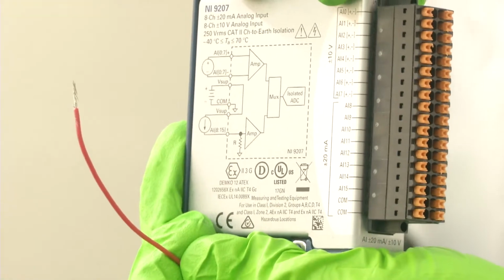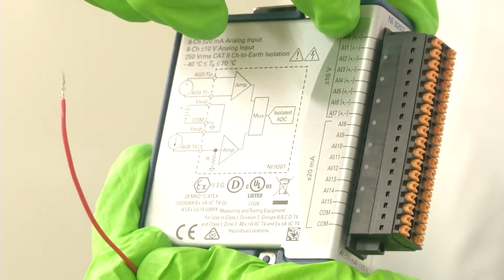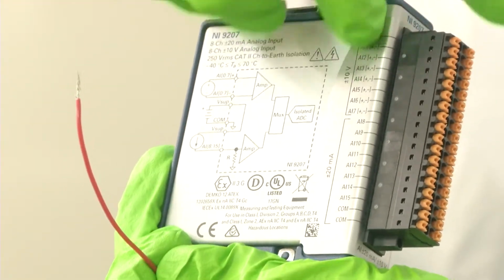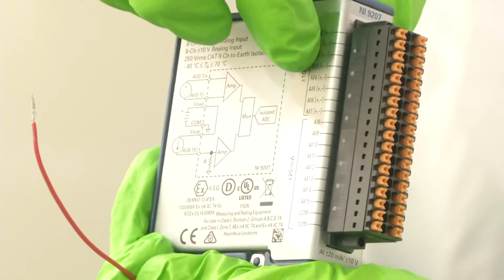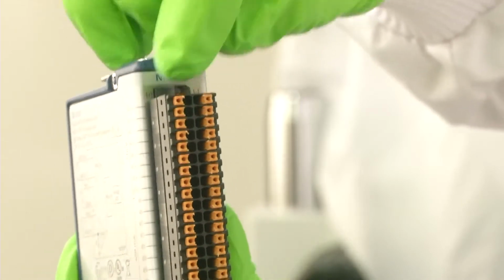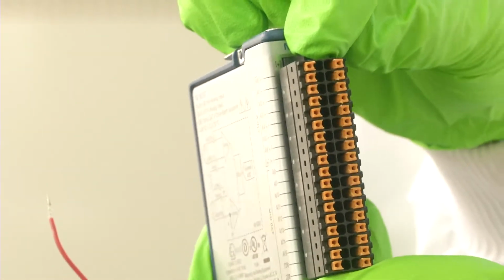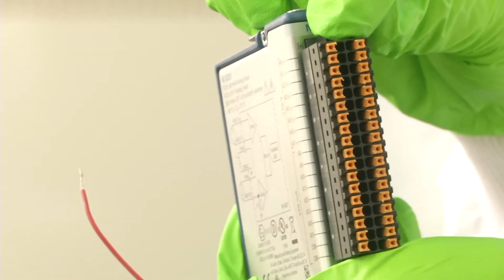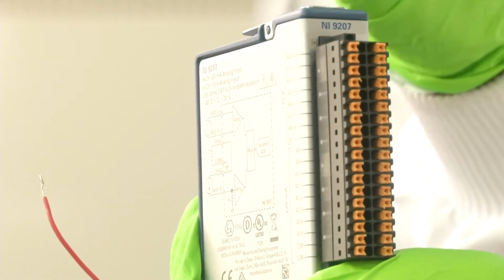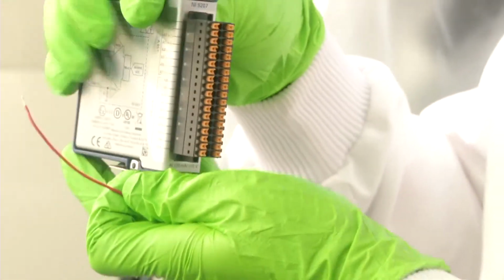So, here if you see there are different numbers of channels starting from 0 to 7. So, in total it has 8 channels for analog acquisition, which can measure up to plus or minus 10 volts. It has both a positive terminal and a negative terminal. What it does is that it can measure a differential input. In some cases, when you are using a quarter bridge, half bridge or full bridge, the voltage signal generated from the bridge is not an independent voltage, it is a differential output voltage. So, if I want to make use of a differential input, one way to do it is to use this device.